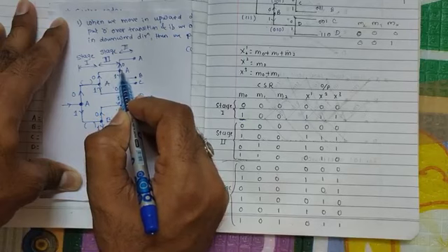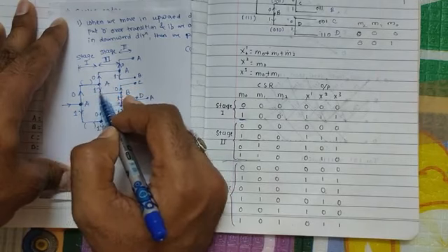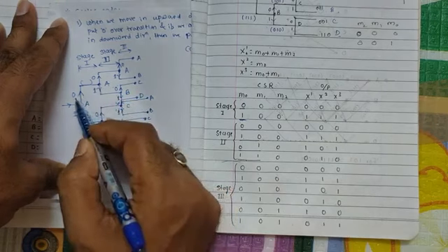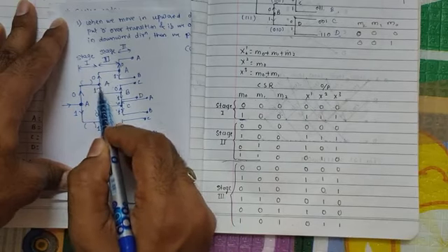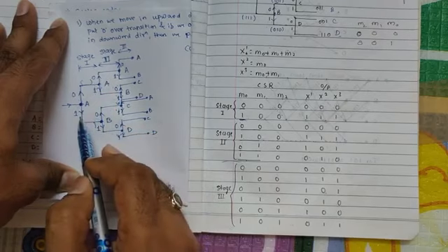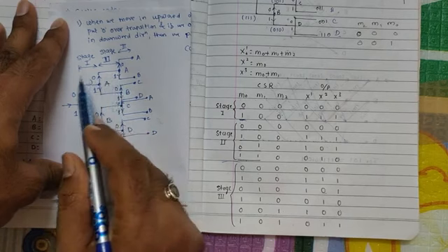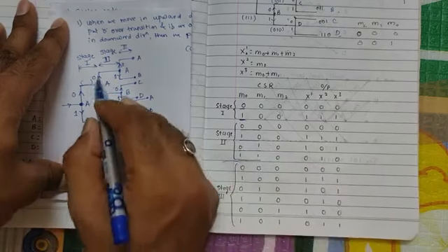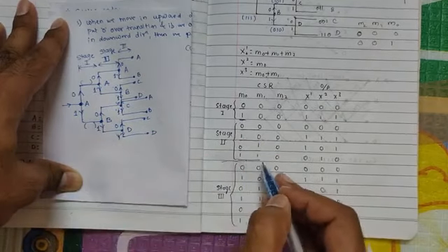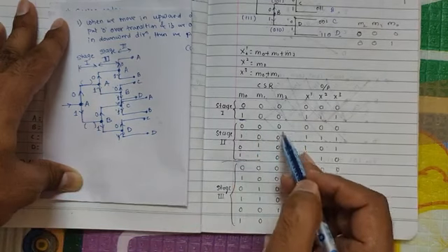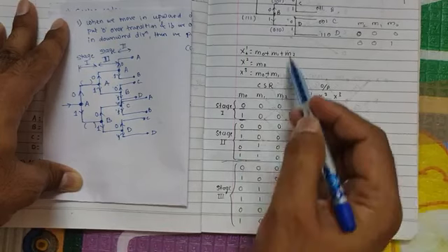So if we see this, these are the output nodes of stage 2, right? So this is input 0 0, next is 1 0, 0 1 and 1 1. So 0 is the main root, and because of this main root we got the two subroots here. So that's why 0 0, 1 0, and because of this main root 1 we have two more subroots 0 1, so 0 1, 1 1. While writing we need to follow from final stage to the initial state. So what I have written here: 0 0, 1 0, 0 1, 1 1. So during stage 2 the content of the third shift register is still 0. Because of these bits we are getting output, which I have written here with the help of same equation.